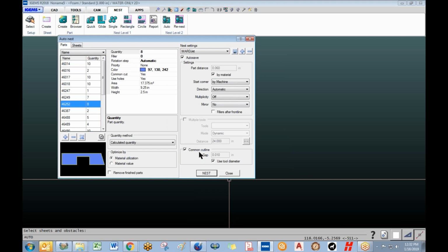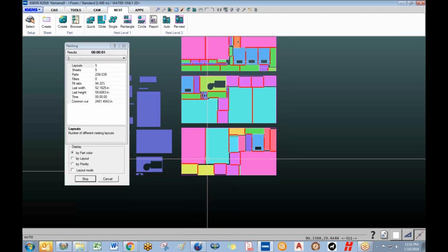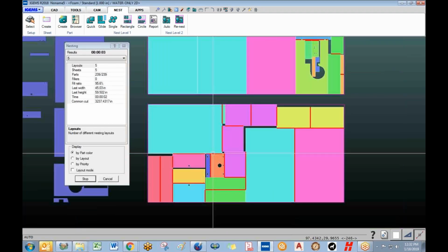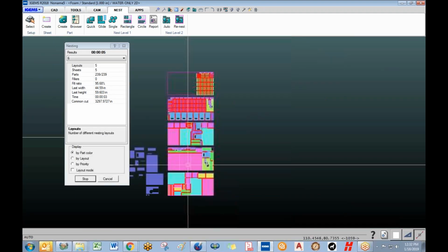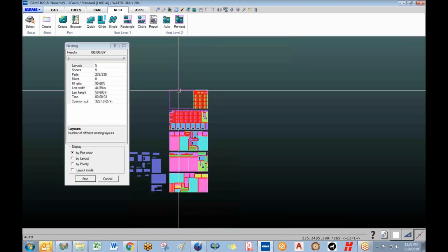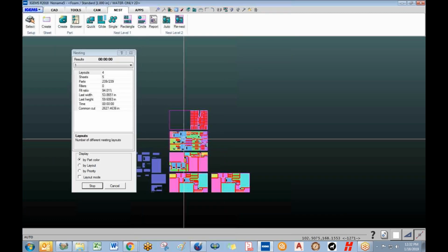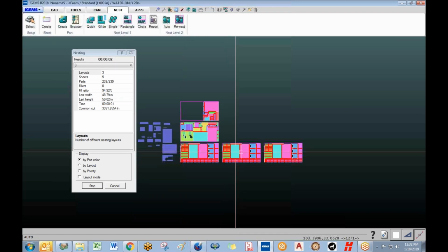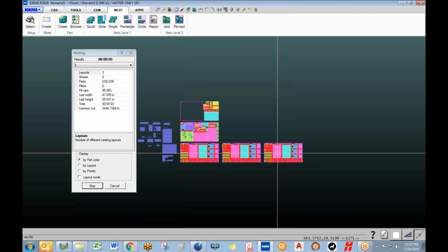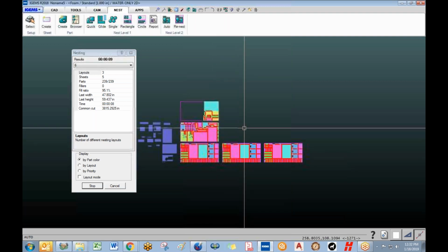And on the parts tab, we're doing common line cutting. So now the gap will be 0.010 of an inch because that's the size orifice I've told it that I'm using right now. And click on Nest. And so it'll go through and do those nests. And this one here shows a little bit better that multiplicity thing that I tried to show previously. So let me just go back, cancel. So if I turn multiplicity on and nest, now it's going to make 3 identical nests there. So the operator will run that program 3 times, and then this once, and then that once.